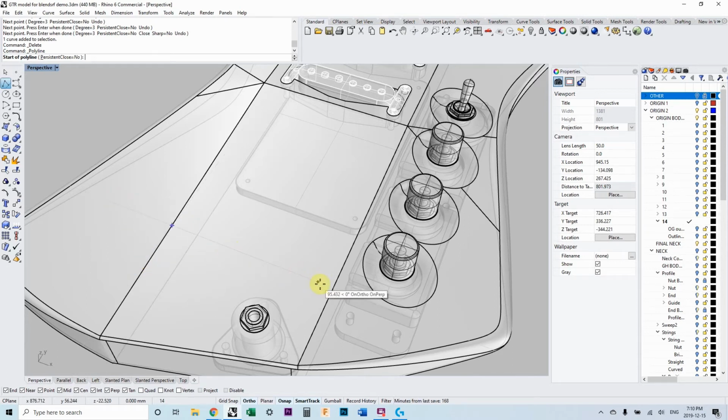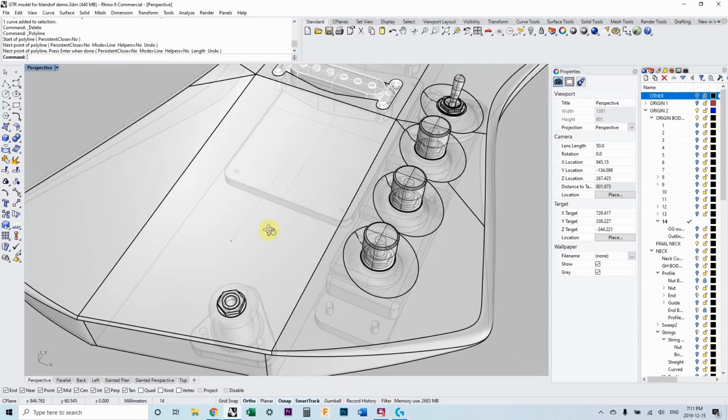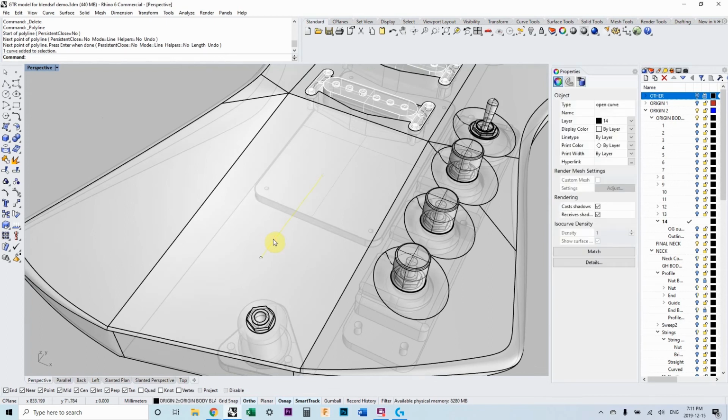And then I can bring that across to this line, and I can press Control again, make sure that it's locked onto that. And now I have these two white points, and I can make a point that's a midpoint between those two points. So that's super useful. I use that feature a lot.